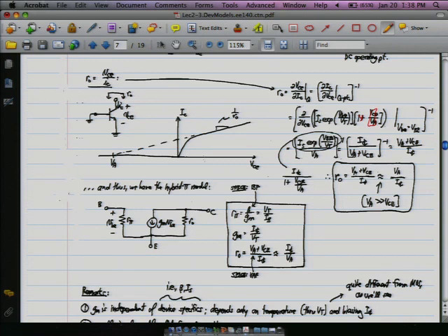So this is not drawn to scale, because usually the early voltage extends much further out, and the VCE is relatively small. So we can say that the sum of those is roughly just equal to this early voltage, because often the early voltage is somewhere in the range of negative 50 to negative 1,000 volts, depending on the quality of the device, whereas VCE is certainly less than your supply, which at most, if you're working with like an audio amplifier, might be 30 volts, but in most cases is more like 3 volts or 5 volts.